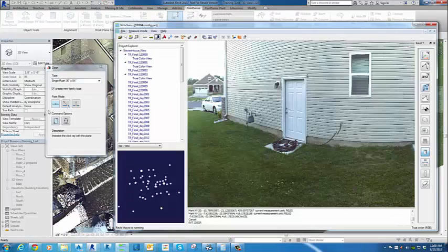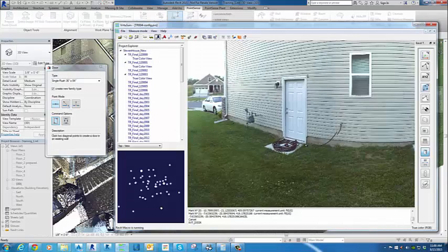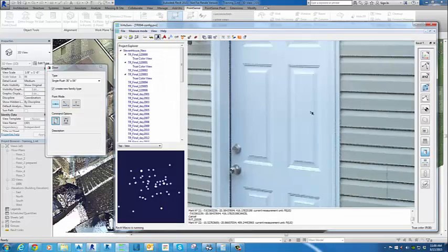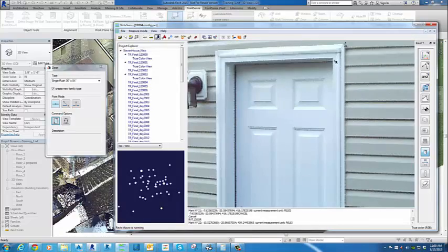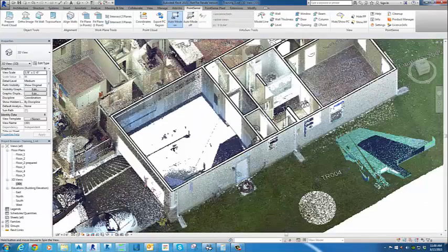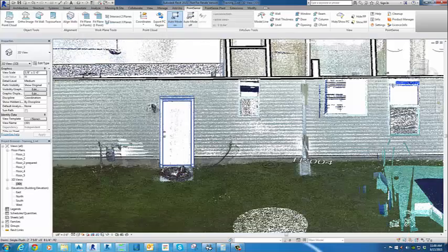But inserting a door, I'm just going to choose a door type, and I'm actually going to create a new Revit family type based on my 2 points that I click. I just click 2 points in opposite angles, and it will send that information to Revit, and it's going to generate a new Revit family door type for me and place it in my model.